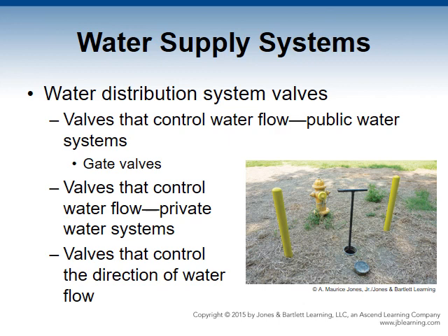These valves have a plate or a disc inside their body called a clapper. When the pressure on the system side is higher than the supply side, the clapper swings back in the opposite direction and closes. If the flow and pressure equalize on each side, the clapper will rest on the valve seat. These valves alone offer little, if any, protection against contamination of the water supply.